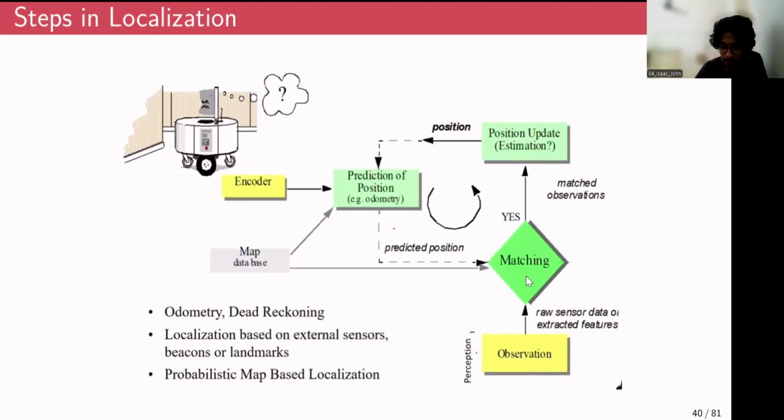Based on the mathematical model, the robot should be moving to the next position. And how much the robot has moved can be acquired from the encoder readings, which essentially give you how much rotation each of these motors has made. Depending on the control input that the motor supplies into the robot, we can estimate the next update or the next position.